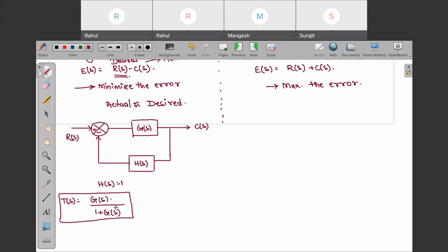So in a negative unity feedback system, Hs becomes a sensor that is measuring your actual output and comparing it with the desired output. So basically it is simply just measuring the actual output. That's it. There is no other process involved in measuring and conversion. So directly we are measuring and feeding it. Or you can even say this only happens. See, so I will tell you, Es is what? Rs minus Cs.